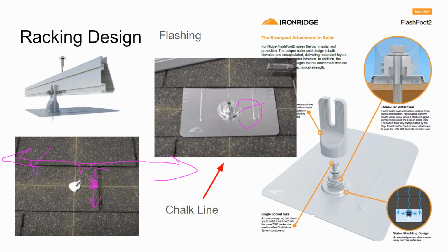And then you pop down chalk lines to determine where those rafters go and identify where your feet are, and then screw a lag screw into that beam. So a chalk line, a hammer, a drill with a small bit for pilot holes, and then a wire to stick down in the pilot hole and give it a turn to see where the rafter is, is kind of the standard practice.